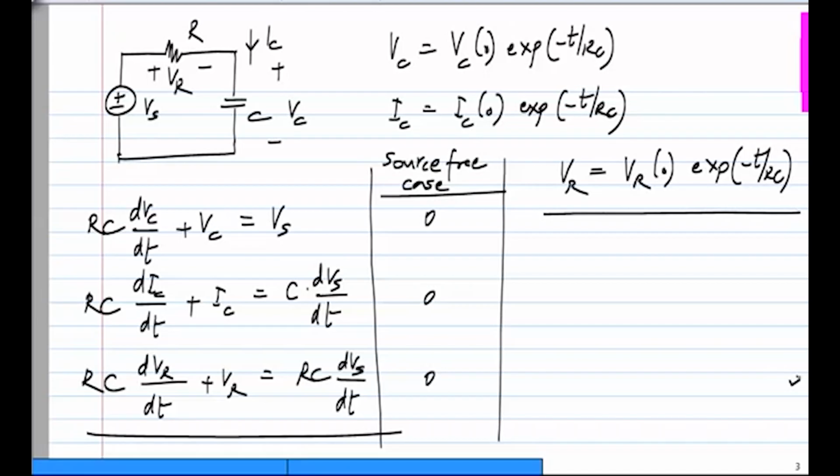So once you are familiar with the basics of a first order RC circuit, you don't even have to write the differential equation. You will be able to write down the natural response simply by identifying the initial condition, which you can do by regular circuit analysis. Now to understand this properly, you need to understand first order differential equations and all the things we have discussed, but after you have enough experience with it, any first order system you should be able to solve simply by identifying the appropriate initial condition. And this is true for any variable in the circuit, because all variables will follow the same pattern as you can see over there.